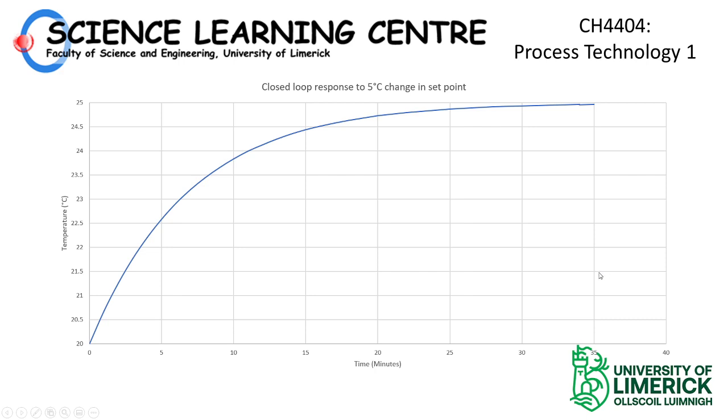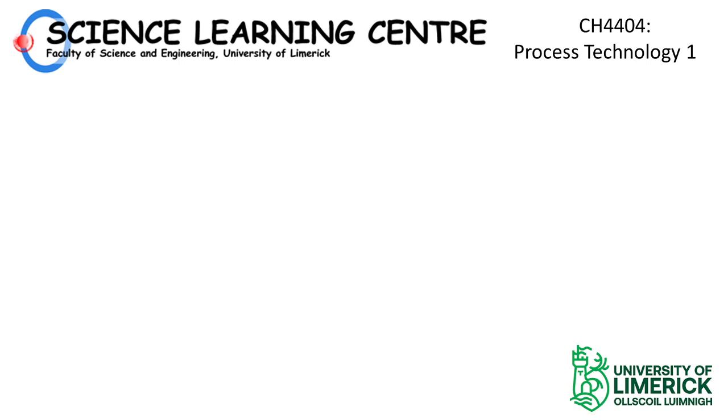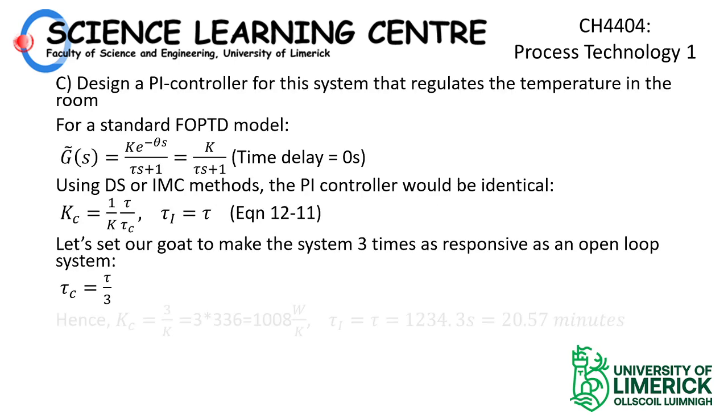If we compare that to the previous case, we'll get there in a moment. Here, after 30 minutes, that's slightly more than 1 tau. That's less than 2 tau, and we still have a long way to go. With respect to the total change in difference, this was a minuscule change, so it didn't make a big difference. But you can see the system has become way more responsive.